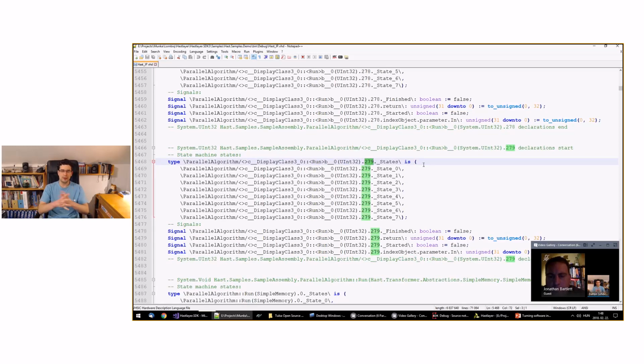And now these are here just the type declarations. The logic itself comes later, but here is where you can see that on the hardware we have those 280 little processing cores. The logic on the hardware, on the FPGA, is actually all running in parallel, not just on 4 or 8 cores, but on 280 cores.